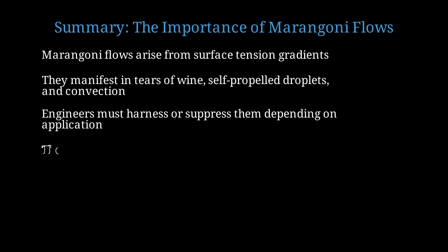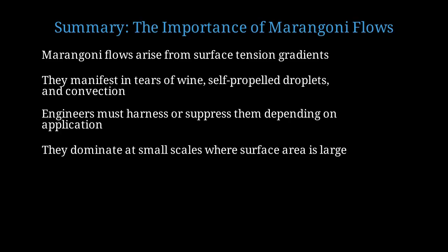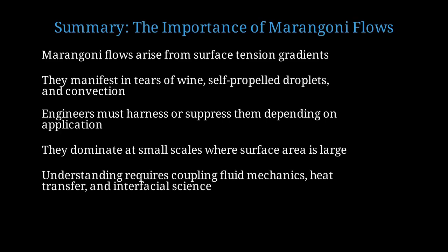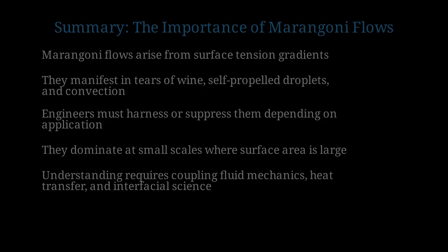coating defects. Marangoni effects become increasingly important at small scales, where surface-to-volume ratios are large, making them critical for microfluidics and nanotechnology. A complete understanding of Marangoni flows requires coupling fluid mechanics, heat and mass transfer, and interfacial science. This makes it a rich and challenging field of research.